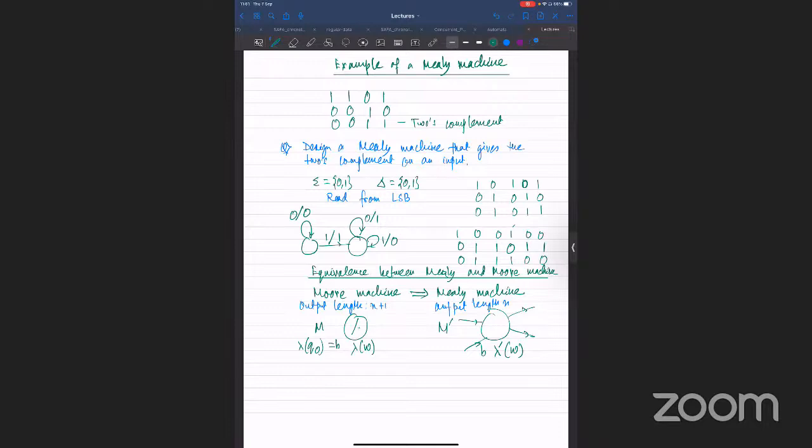How would you translate a Moore machine to a Mealy machine with this assumption? So you are going, let's say, from Q0 to Q1, from Q1 to Q2, and here, let's say the output is 0, 1, 0. And all you want is to output, like the initial, you can forget, it's the B. You want to output on the Mealy machine a 1 and a 0. So what is the general translation?